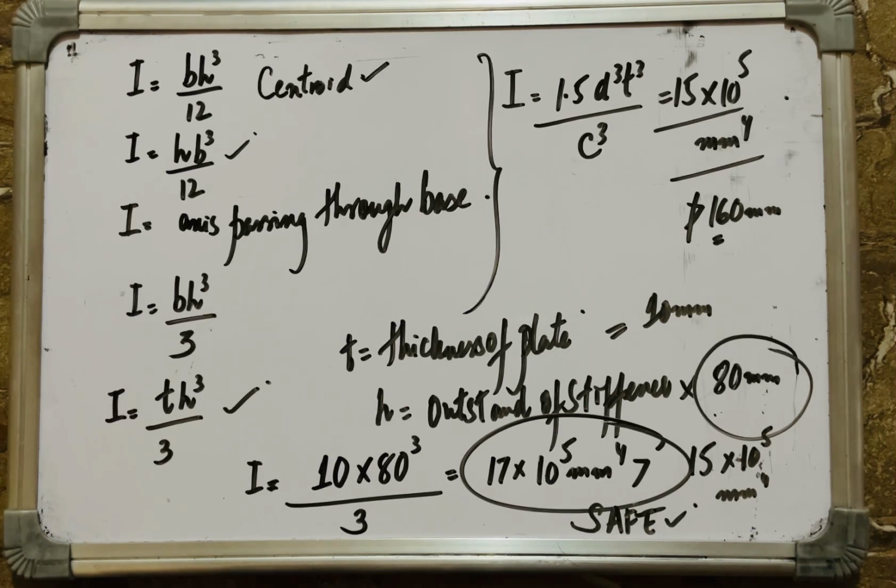And in addition to preventing web buckling, they also improve the overall shear capacity of the structure. Our d by t ratio was greater than 90. We chose the spacing, and we also checked for the greater unsupported panel dimension of the web. And these intermediate stiffeners, which is the vertical stiffener in our case, are designed to have a minimum moment